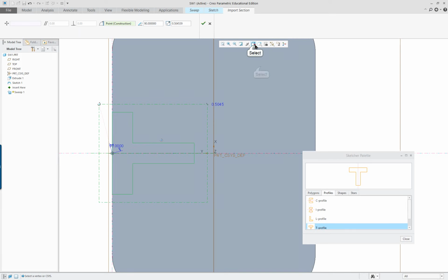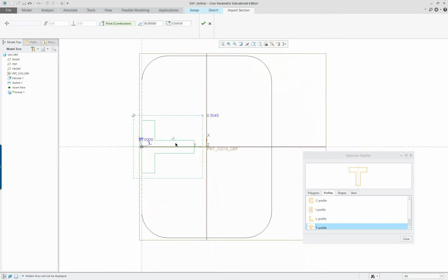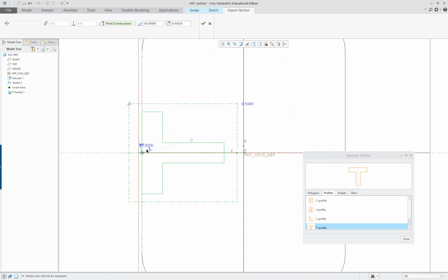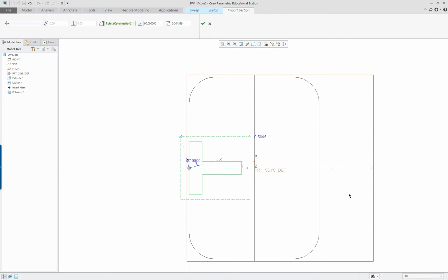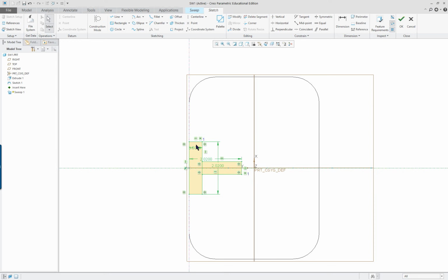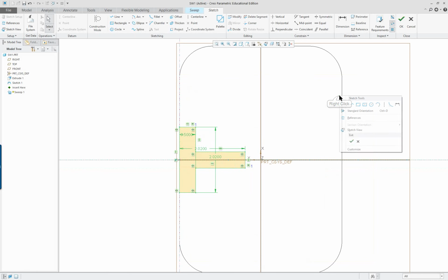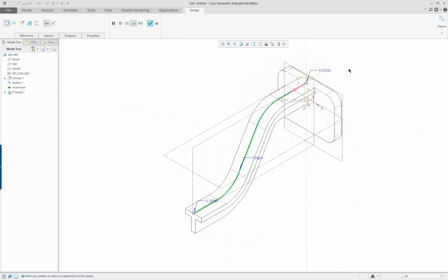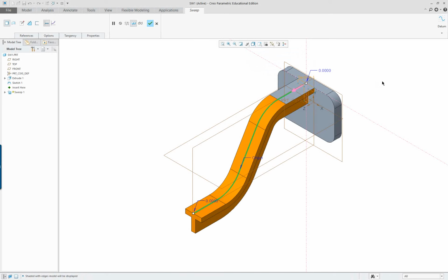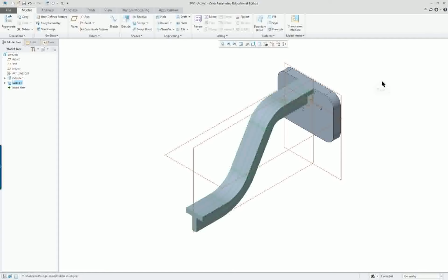And it looks okay. Now let's go to no hidden just so we don't have to have all that shading there. So it looks okay. Close. I'm not going to go through and put in all the correct dimensions. You can make things equal, whatever, and you're going to put in your rounds, but I'm not going to do that here. So check. I'm going to go Control D. You can see the preview of it. Shading with edges. Looks good. Middle mouse button to finish it.